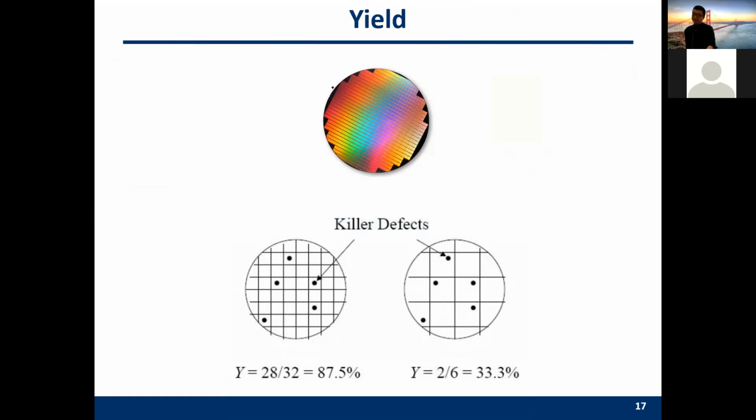And when we consider fabrication, there is a concept of yield. Yield means the percentage of good chips out of the total chips. When you fabricate your chip on this die or this wafer, inevitably you may have some defects, and the defects may obey some normal distribution. From this figure, you can see that if you have a very large chip area, this is your yield.